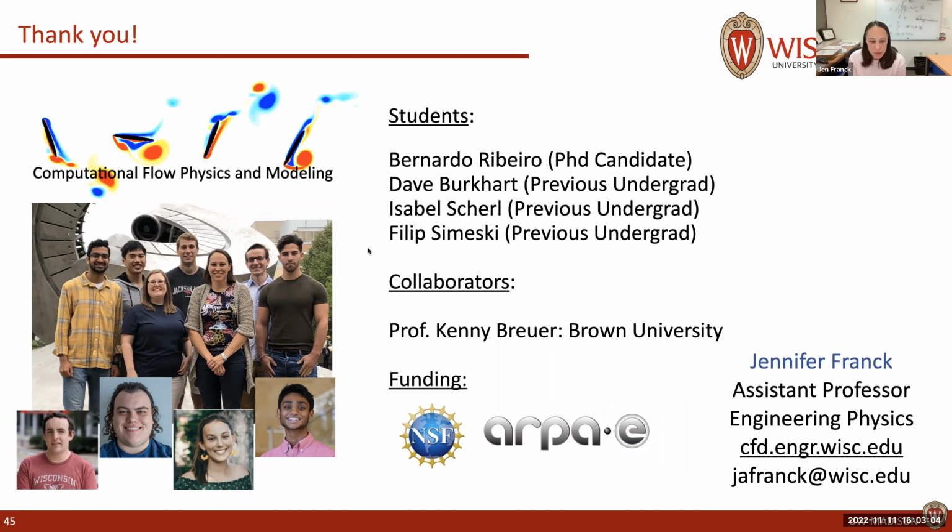I think what we would like to do is to be able to have a reduced order model for that vortex blade interaction and then combine that with, or utilize, a neural network to give us a predictive capability to say, we want the foil to circumvent the wake, or we want the foil to interact with the wake at this timing. And then we would be able to use the reduced order model to compute the lift benefit, or the delta CL one way or the other, or the delta power.